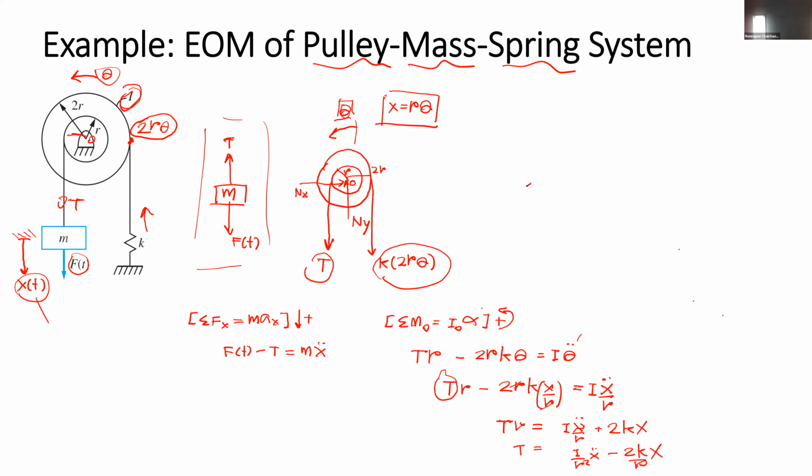This is the force. The magnitude of the force is the spring constant multiplied by the linear displacement. The linear displacement is 2r multiplied by theta.